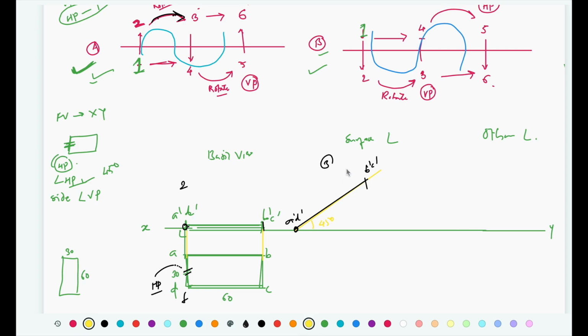Now once you have got that second front view, to draw step number 4, project points from this front view, project points from the first top view, connect the respective points and complete the view. So this is A, B, C, D. This was the front view, step number 2.